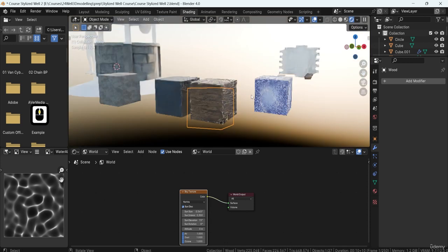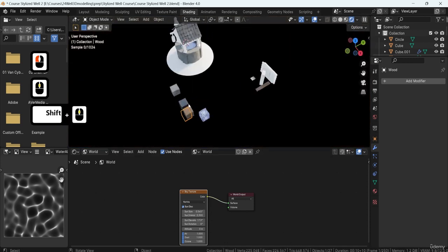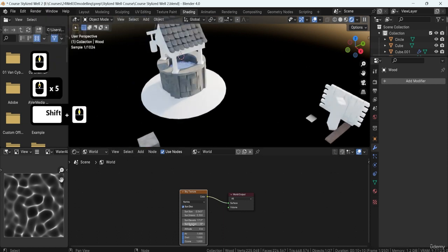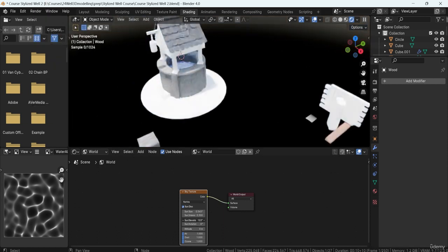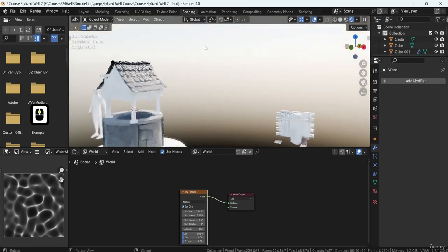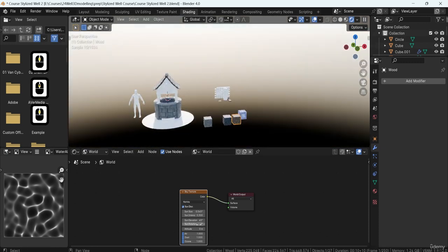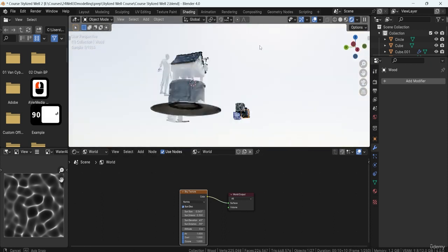Sun elevation is basically how high the sun is. We can control the height of the sun, and we can see through the shadows over here how it's going to look. If we increase it to a value of 90, it's going to be right above us. So that's how it works. I'm going to set this to something like 45 degrees. That usually works and gives us a nice diagonal angle. The rotation is basically, 0 is the backside, and the right side is 90.